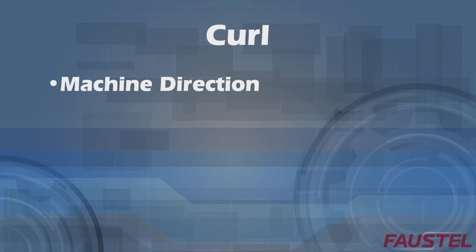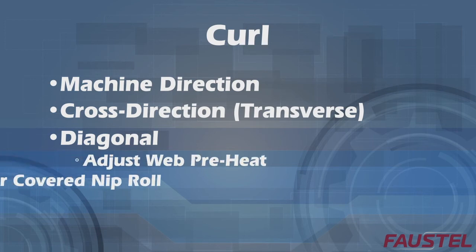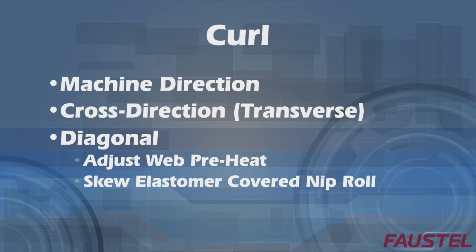The second and third types, cross direction or transverse, and diagonal curl, are more difficult to control. Efforts to improve optical quality usually lead to ever-increasing combining temperatures. Transverse curl then becomes a frequent problem. As pressures are increased, the non-uniform width footprint leads to the development of diagonal curl. Web preheat and the ability to skew the elastomer-covered nip roll are the tools frequently used to eliminate this type of curl.